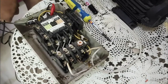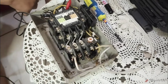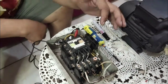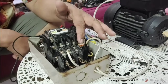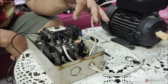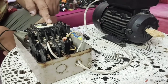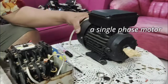And this is under the full voltage magnetic starter, where the motor will immediately receive 220 volts. Then you have the overload relay. This is the protection, the protector of your motor. When an overload occurs in your motor while in operation, this one will take care to trip or to stop the motor. Then you have here the push button. Okay, so let us say we have here the motor, the single phase motor.